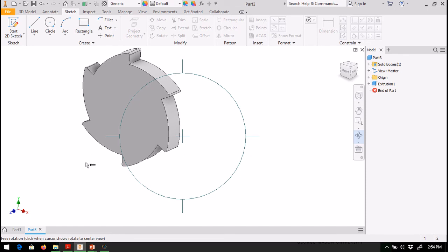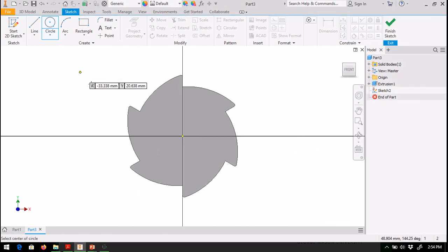So the first thing I'm going to do is create the 6 millimeter hole that goes all the way through, and then we'll create the counterbore and then the protrusion on the back side. So let's create that hole. So click on circle, and then anytime, again, you generate a two-dimensional sketch, you need to select a sketch plane, and we'll select this front face here.